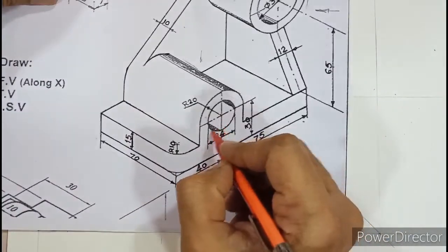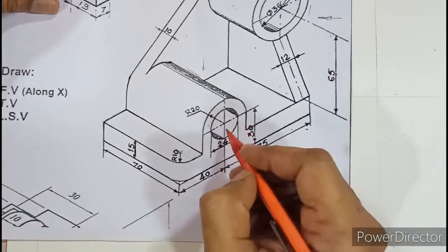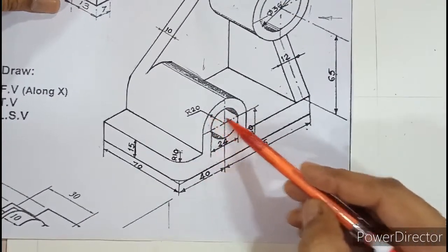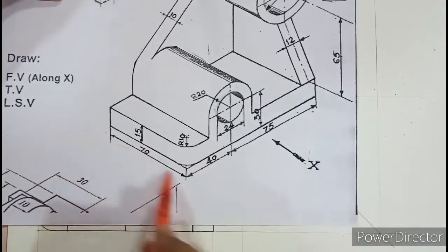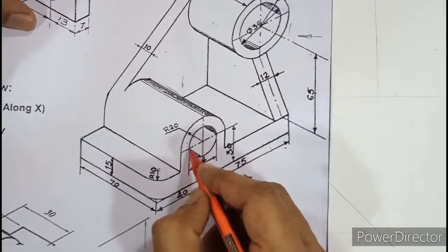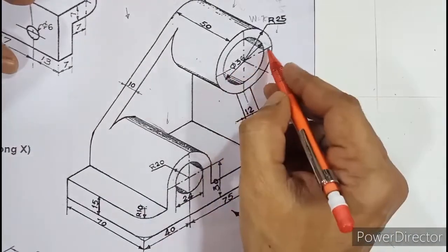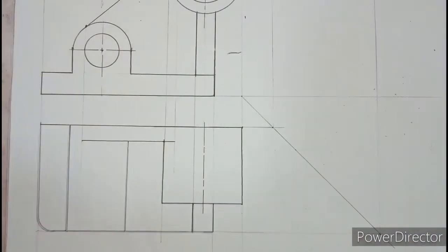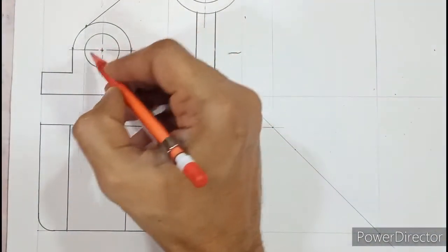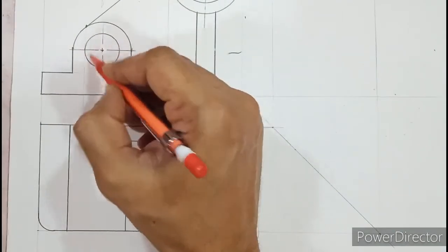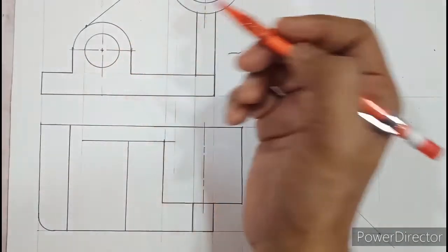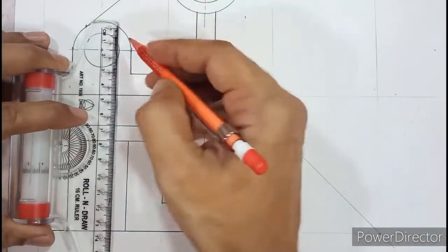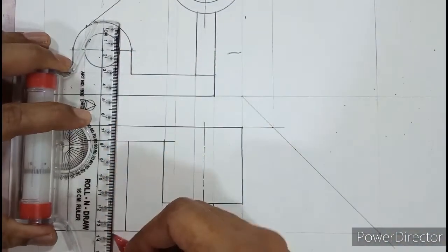Whereas if you look at this circular edge, the depth of the hole is again not specified. But again if I put my pencil from here, it should come out from the other side. So the width has to be 70. So this 1, 2, 3, 4 hidden lines can be drawn corresponding to the circle, and that can be easily made out from the question itself. So this is that circle which belongs to the semicircular portion. So if I can extend this and draw a hidden line, so let me first extend it light.